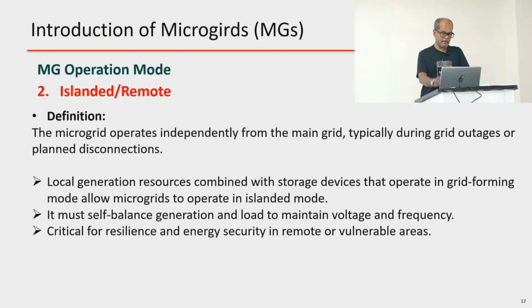And again, this is the islanded case, when it is not grid connected. During that time, only the local generation is going to supply power to the local load. If there is enough capacity, it will supply all the load. Otherwise, as I said, you can disconnect non-critical load from the system.